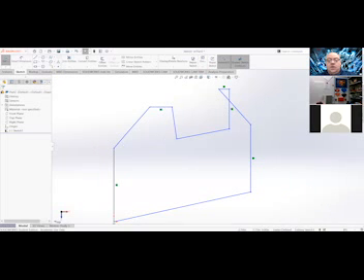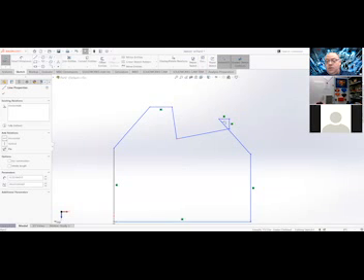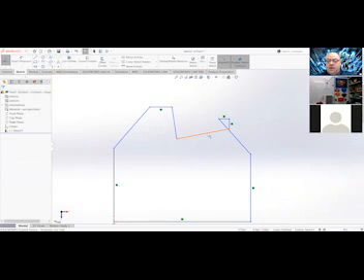Okay. So next, I'm going to go down to the bottom one because, hopefully, I'll pull this apart. This bottom line is definitely not horizontal. So I'm going to select that. I'm going to select the horizontal constraint. That's getting worse. That's okay. Don't worry about it. The next line is, I also want this line here that I've got right orange. This one needs to be horizontal. Notice I've got two black lines now. So things are getting better.